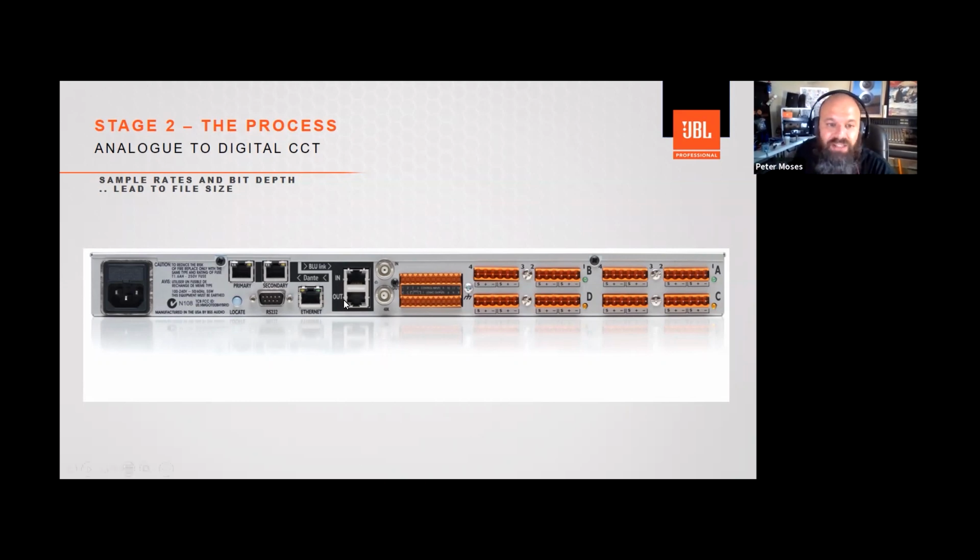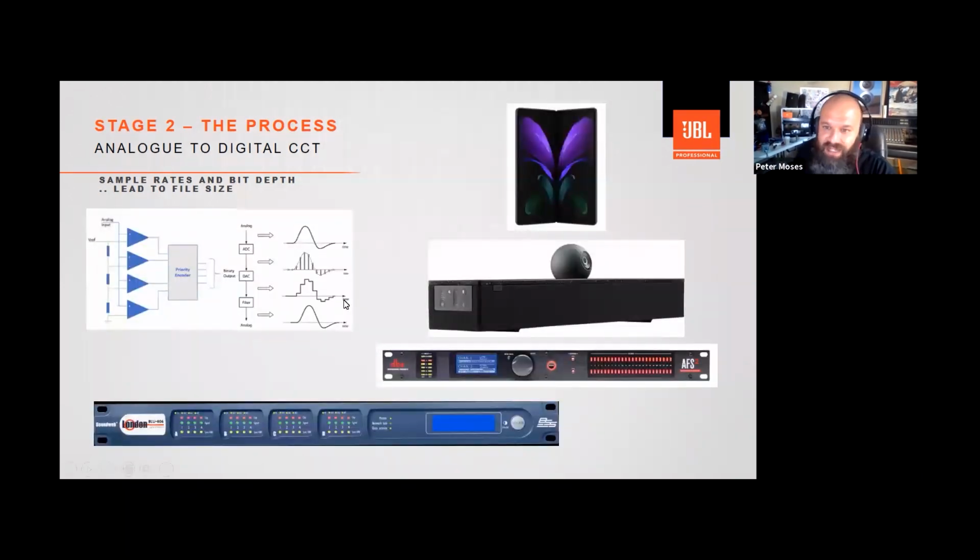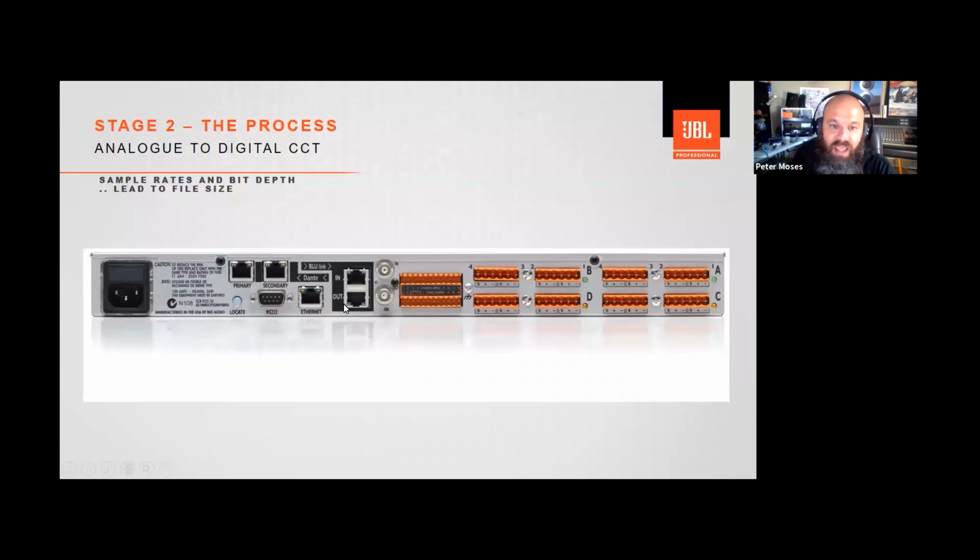Moving forward, it's not just the primary and secondary Dante ports. It's also, in this case of the 806, HARMAN's BlueLink port. HARMAN's BlueLink port does not allow you to push and pull information through a switch or a router. Indeed, it is designed to be a circular network topology, going from a BlueLink in to a BlueLink out of another device.